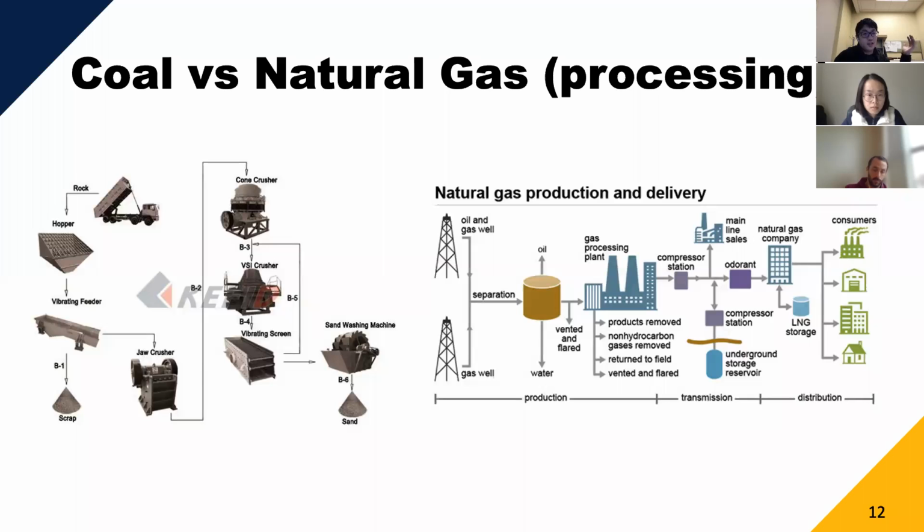So the coal that gets extracted from all of your mining facilities gets shipped over to, oftentimes, directly at the power plant. It goes through some hoppers in order to filter out any non-coal materials, gets ground up into finer and finer powder, and eventually will feed into the combustion chamber at the power plants, which we'll look at in a bit.